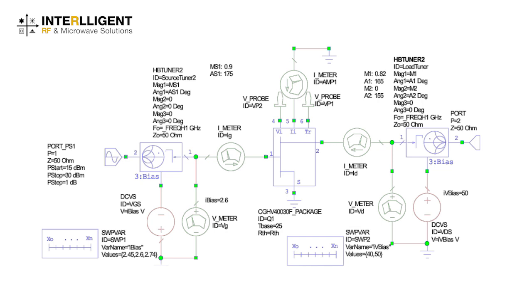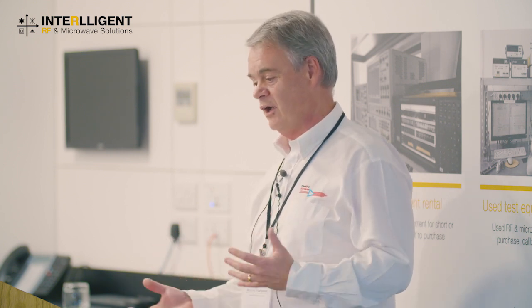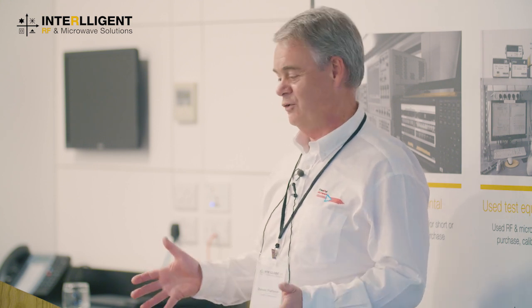A lot of research work has gone into harmonic source pull, but I don't really think it gives any significant benefit. There is some things you can do with limiting overdrive conditions and making the device a bit more rugged, but also source pull is quite a difficult one to try and achieve, so I'm not going to bother doing that.